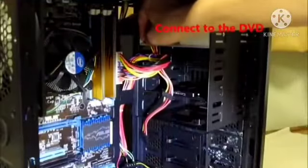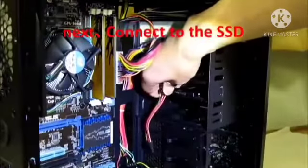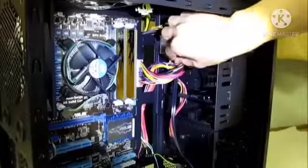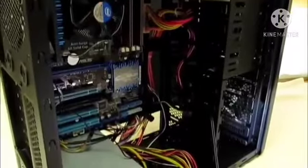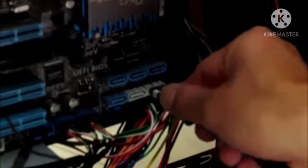Step 12. Connect cables. Every device that has been installed needs power. The motherboard has 2 power connections, and there are 2 connectors specifically for SATA devices. The other connector will run fans and other non-SATA devices. Data cables connect the drives and front panel devices to the motherboard. Please consult the motherboard documentation for the exact placement of connectors.